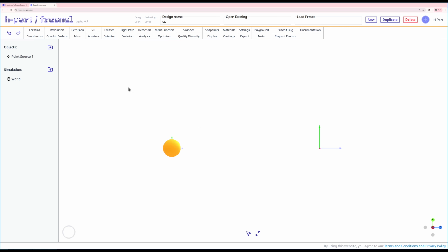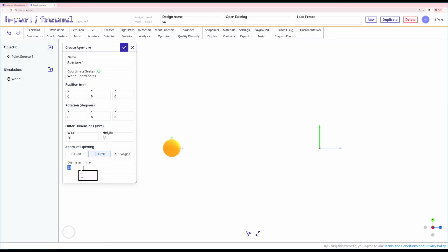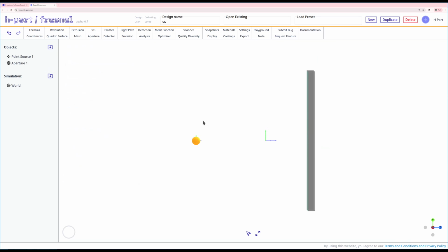And then I'm going to create an aperture. Now we haven't worked with apertures very much, but they effectively act to block the light, and we're going to use it here to neck down the light so the light that enters the prism and thus our spectrometer is roughly speaking paraxial. If we didn't have an aperture, we get a lot of light near the edges of our lenses, and the aberrations would ruin the performance of our spectrometer. So let's go ahead and create a basic aperture here. And we're going to put this at about 15.